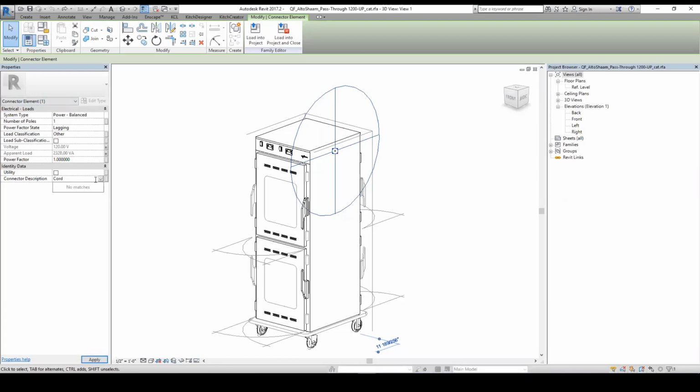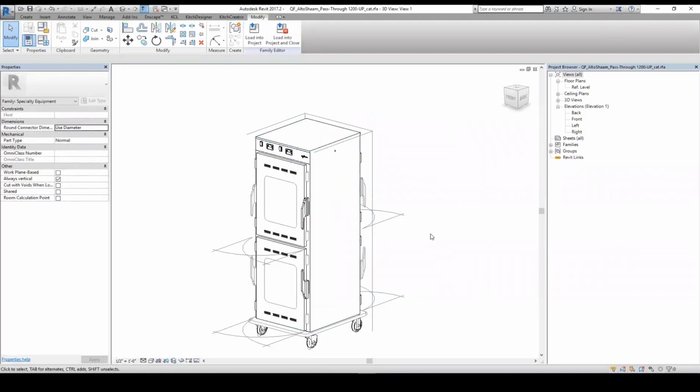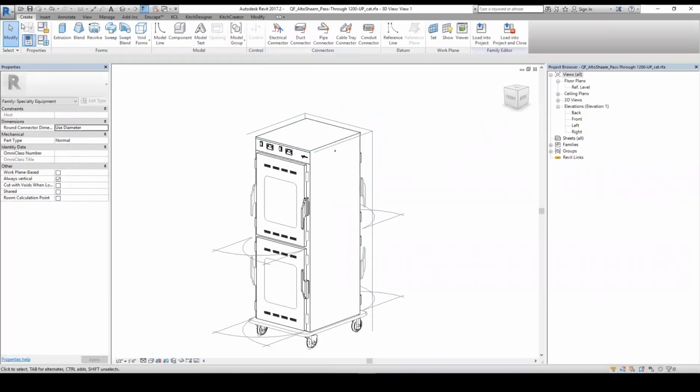And here you can type in whatever you want. So it's a field that you can fill in if you would like, and then you can look for that to place connection points based on if this is filled in. So if you wanted to add connectors to some of your families, it's not a hard thing to do. Just on this Create tab over here, there's 5 different types. We're mainly only looking at these 3 types.